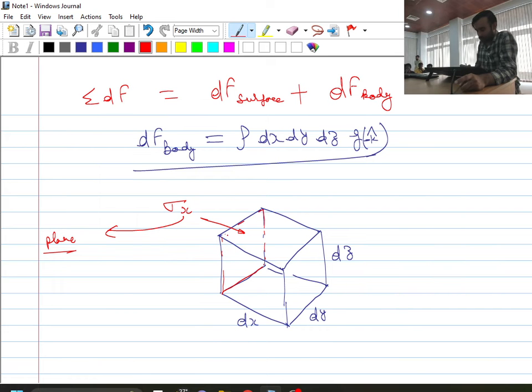Perpendicular to this particular face we have the x direction, that's why I am calling it the x plane. Then I also have to mark in which direction this stress is acting. Of course this stress is also acting parallel to the x direction, so I will write it as sigma xx. Let me show it with tensile nature. This is my sigma xx over here. Is this one clear?